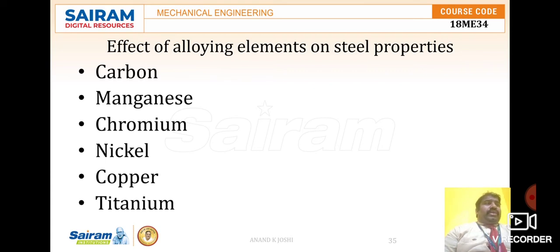As the carbon content increases, the metal becomes harder and acquires greater tensile strength, and becomes increasingly responsive to heat treatment with further development of the strength and hardness of the material. However, as the carbon content increases, the ductility of steel decreases, making it more brittle.